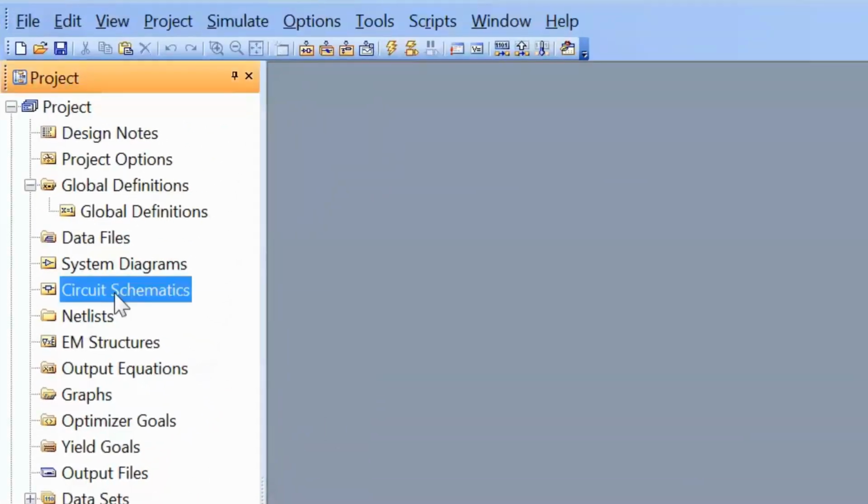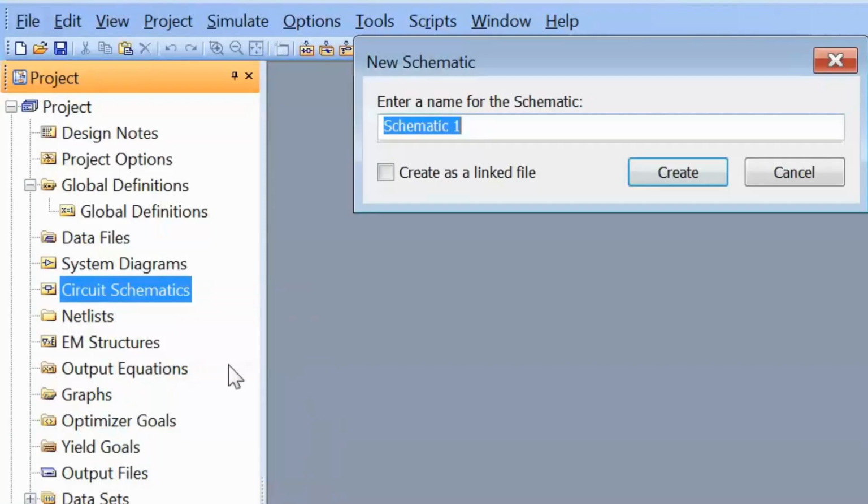So let's open a new schematic, and let's call it TX line match. And then the first thing that we'll put on, as usual, is a measurement port. Press Ctrl P and insert the port here. In this case, we'll carry out a match between a resistive port, which has got an impedance of 50 ohms, and a load which has got a complex impedance. This is nothing but a special case of two complex impedances, and there will be no loss in generality in doing the match this way.